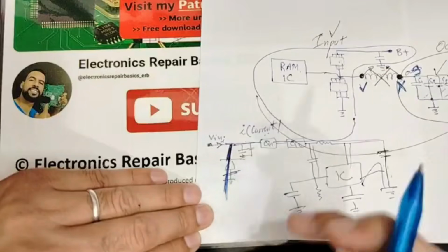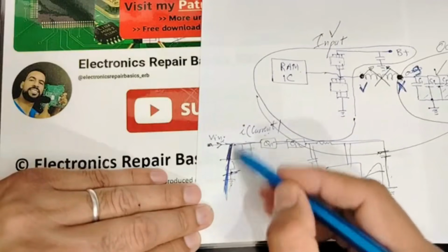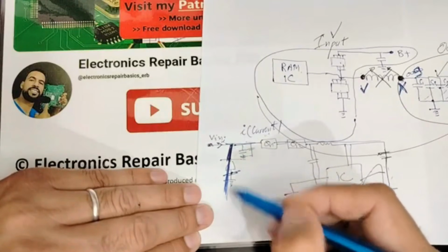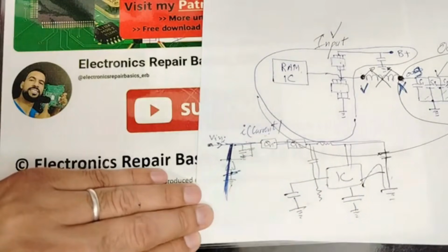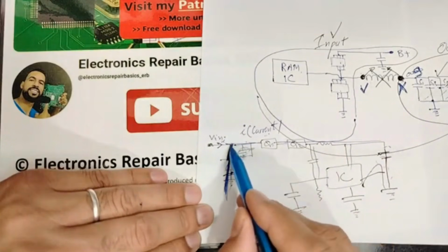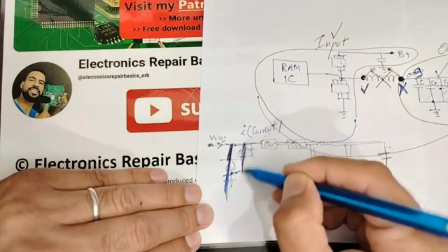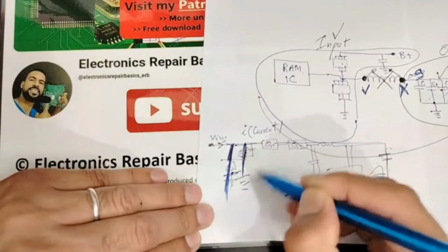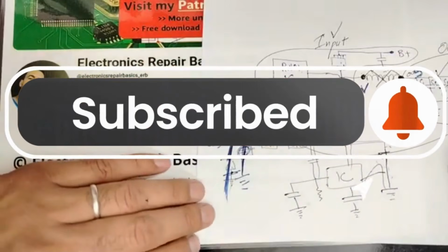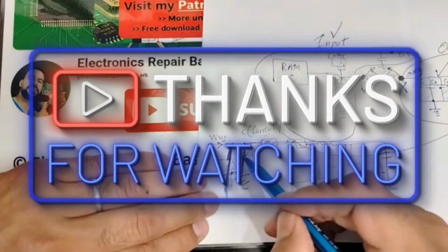It means this one will be burned out, will be very hot, because the current goes into the low resistive path. But if this one is good, and for example, this one is the bad one, it is the same. Here a little bit of current, here a little bit of current, and here a lot of current, because this one is connected to the ground, and this one will be very hot. This is how the voltage injector works. And of course, with the thermal camera, you can see the hot components.